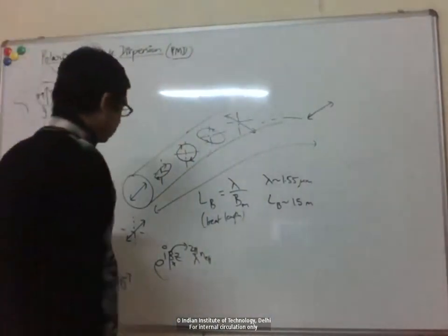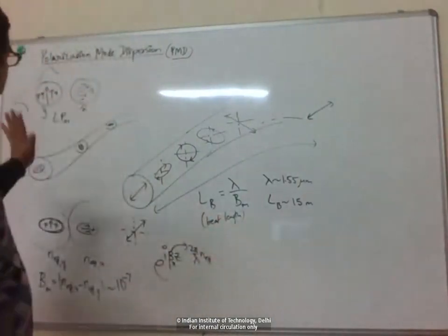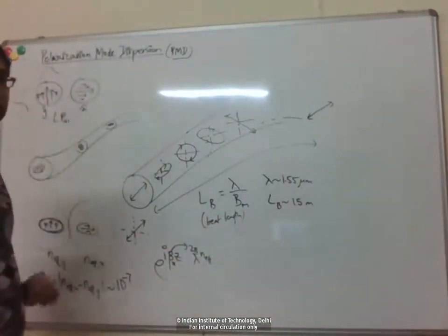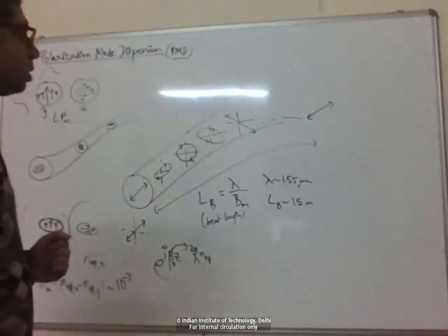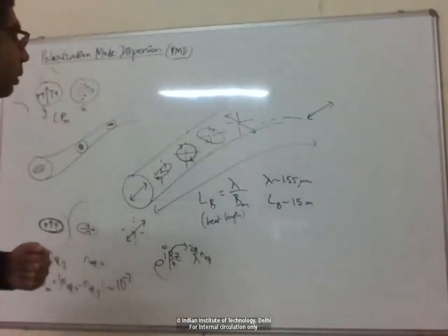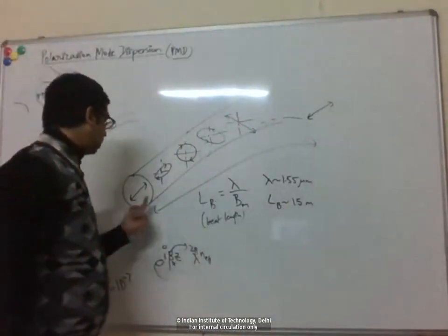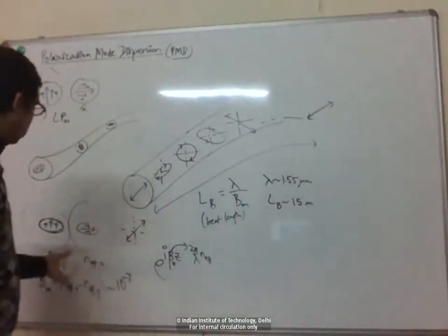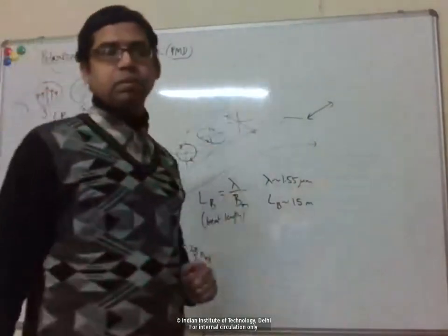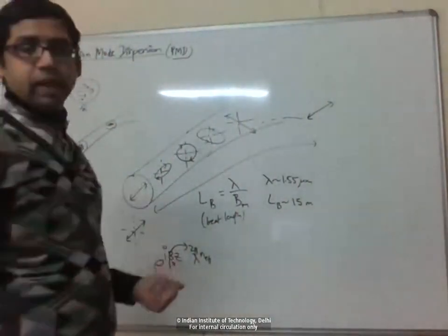So just from this, you can sort of see that the polarization, we launch some input polarization, typically linearly polarized at the transmitter end, but that doesn't remain. The polarization is not preserved as the mode is propagating in the fiber, right? And this is again for a constant birefringence, right? What happens is that the birefringence also keeps changing along with it. So that makes the situation even more complicated, right?